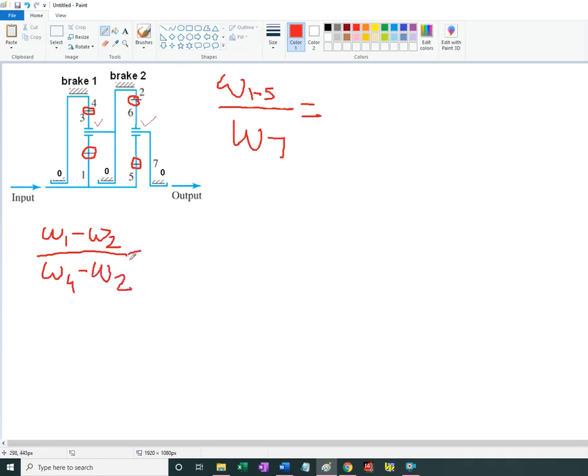And in terms of number of teeth, we've been here before, so it will be negative number of teeth of gear 3 of the planet. Doesn't matter. All it does is change the sign, so it will be negative n3 over n1 times positive n4 over n3. n3 cancels out, so I have n4 over n1.